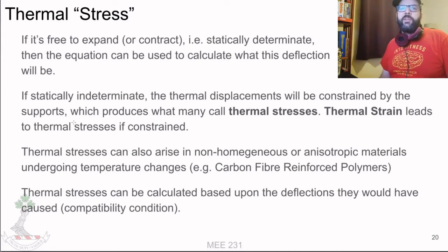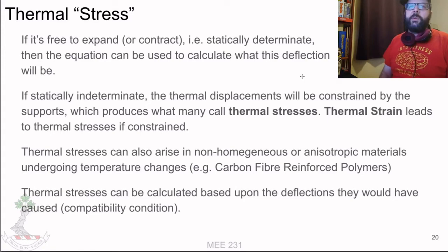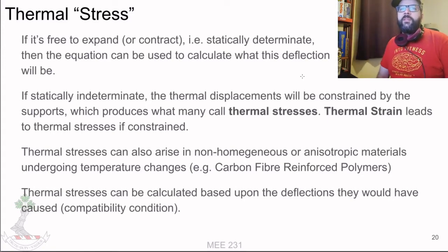If, however, this is a statically indeterminate problem, and this thing's mounted between two things, or if it's held in place in a manner that doesn't allow it to expand or contract, then the thermal displacement will be constrained by the supports, and we get what a lot of people call thermal stresses.